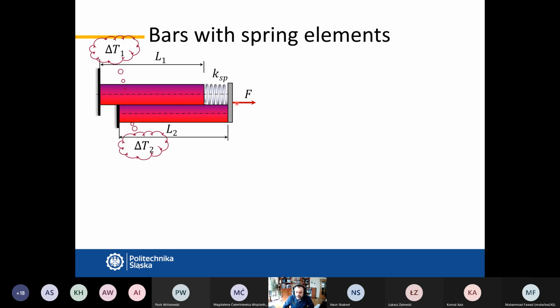There can also be a force applied at the end, but between one of the members, bar number 1, and the connection surface, there is a spring introduced of given constant K. So of course the change in length of the entire system, measured here at the end at the plate, is the change in length of member number 1 plus the change in length of the spring.